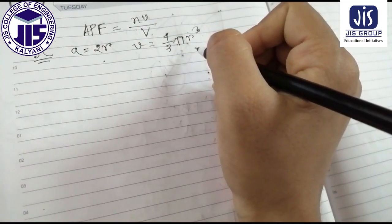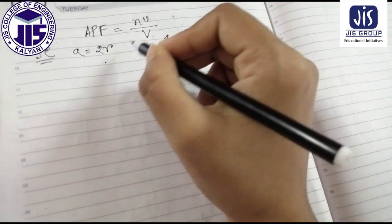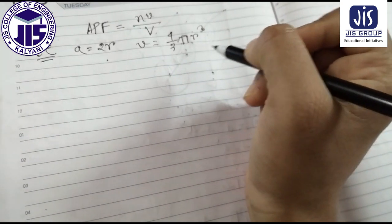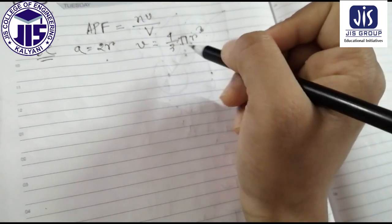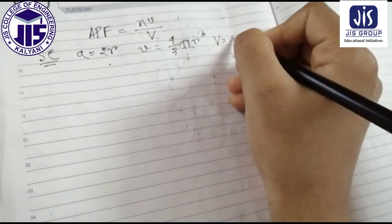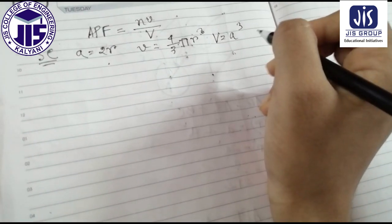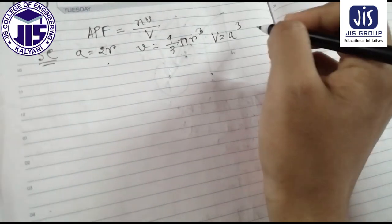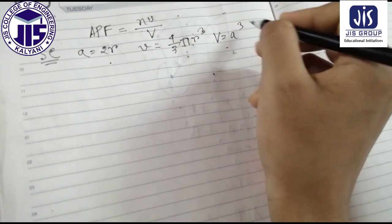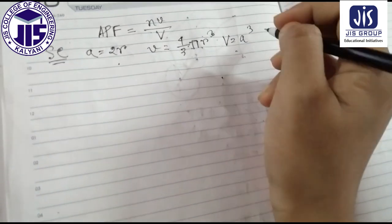Because the shape of each atom is a sphere, so the volume of that sphere is 4/3 pi r cube. What is capital V? This will be a cube, because this is a cubic unit cell. The length of each side is a, so side cube is the volume of the unit cell, since it is a cubic unit cell.